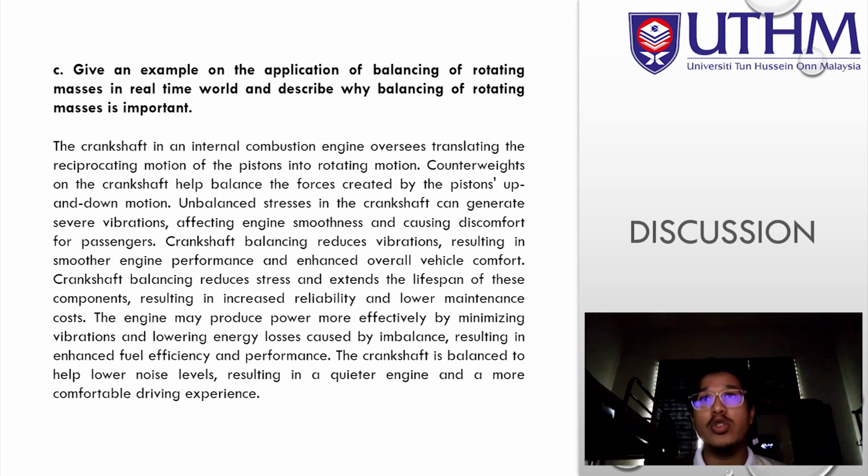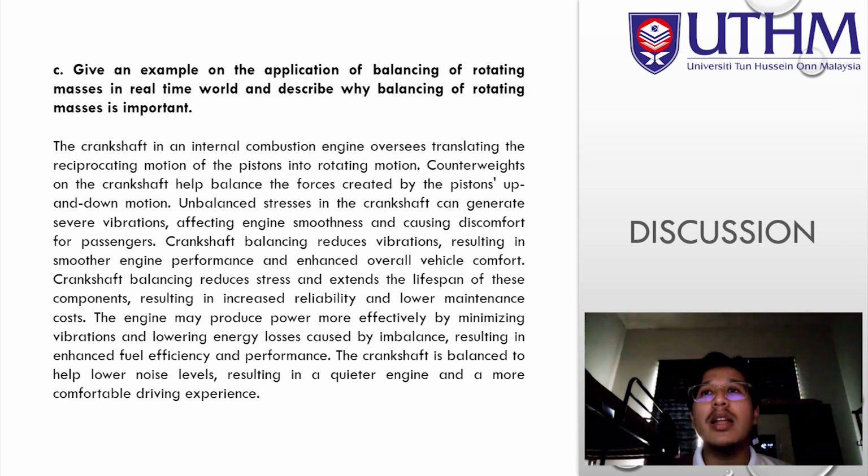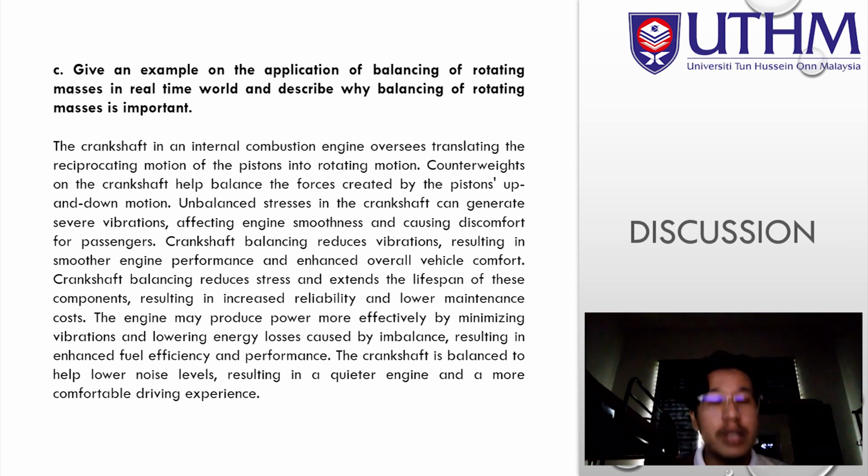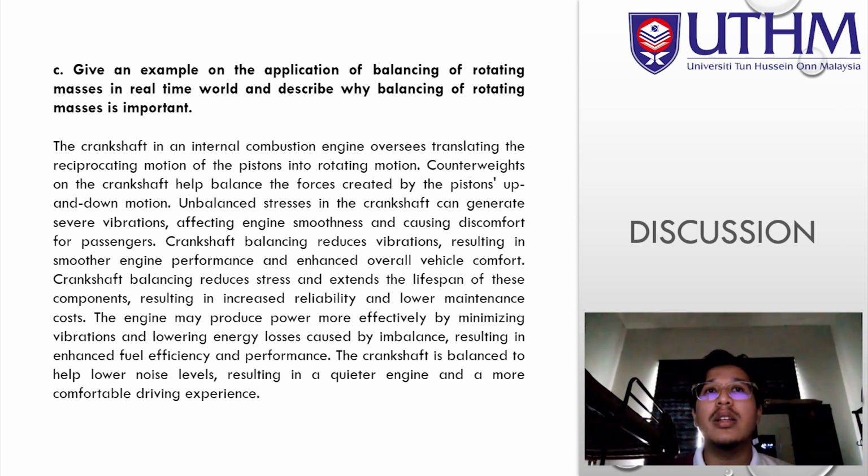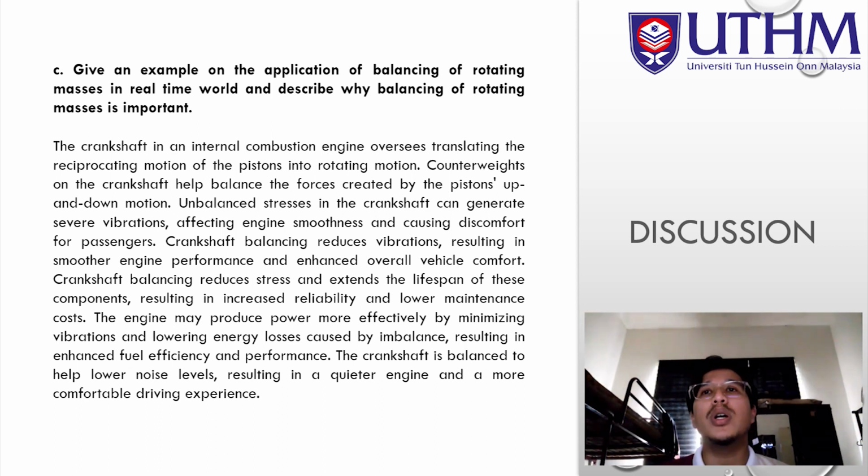Engines may produce energy losses caused by imbalance, so balancing results in enhanced fuel efficiency and performance. The crankshaft is balanced to help lower noise level, resulting in a quieter engine and a more comfortable driving experience. That's all. Thank you.